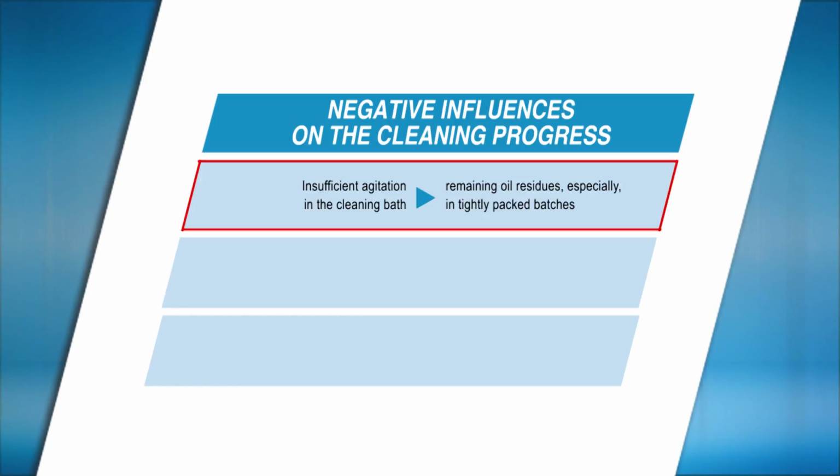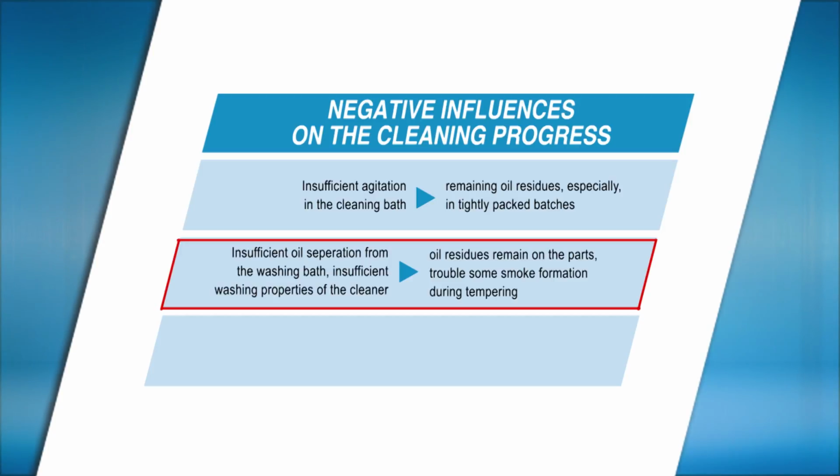When agitation is inadequate, it may influence the cleaning of parts, particularly when the parts to be cleaned are immersed in the bath in a tightly packed condition. Care has to be taken to ensure oil residues on the parts are properly cleaned by the use of suitable cleaner, as otherwise these residues can cause smoke formation during subsequent tempering processes.